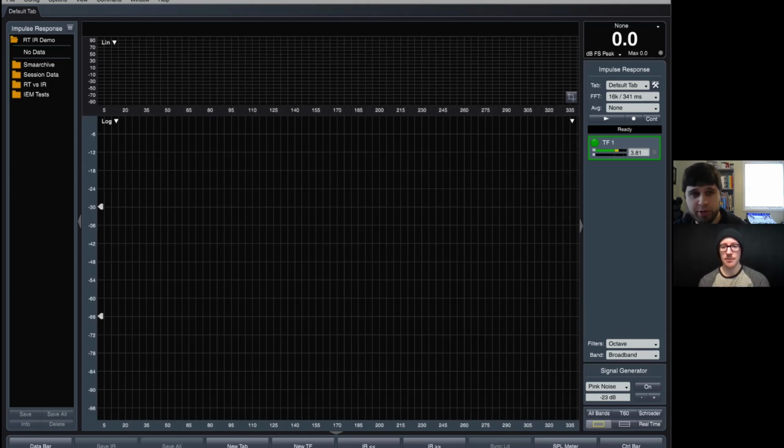The three parameters we're going to look at here are, first, changing the FFT size. Using a longer FFT will give us a better signal-to-noise ratio. Second, adding some averages. If you're familiar with EQ Wizard, both of these are parameters that you can control. You can say, I want to use a longer sweep, and I want to use more averages of that sweep. And then the third parameter we'll look at is what happens when we change the signal type.